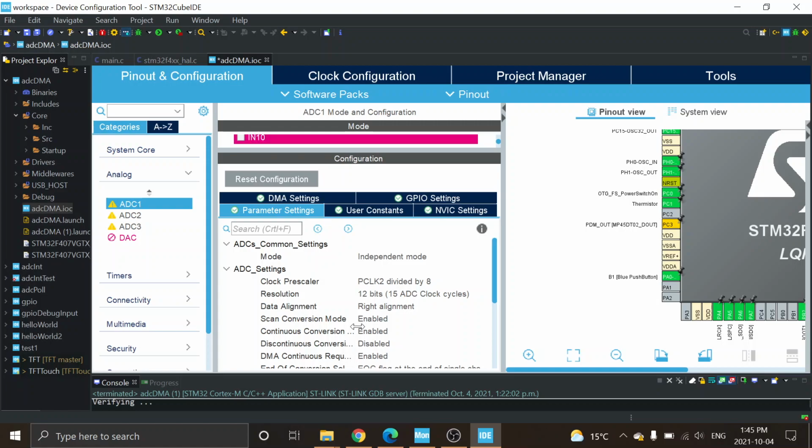We could just say, use the DMA, do it once, put it in a while loop, and keep having our software do it. But the whole thing about this separate piece of silicon is I can just say, just keep reading me values. So I want 100 values of my internal die temperature, and 100 values of my thermistor, and just keep reading them. So 100 values of each. Just cycle through as fast as you can and stick them in some memory location.